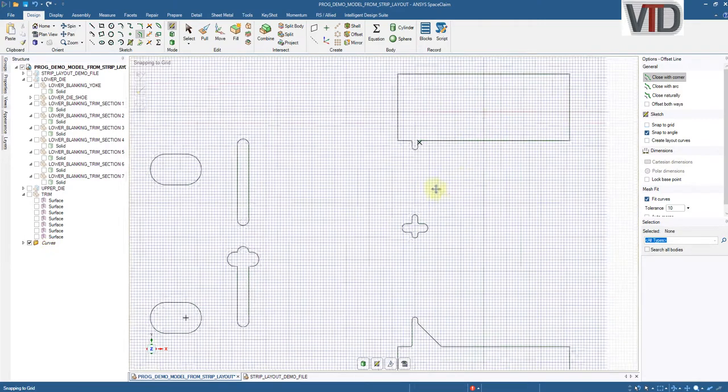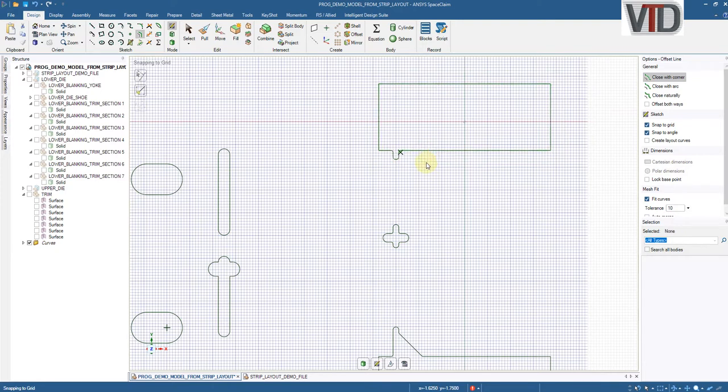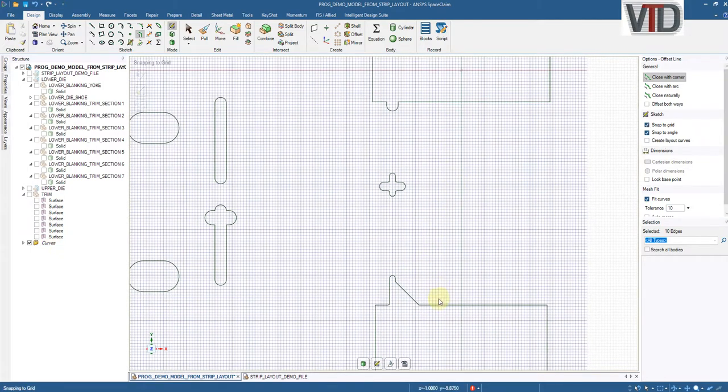Now with this one here, when I double clicked it the first time, it saw that there was basically two viable options here, and it decided to just pick the front face. Now if I hit escape and double click again, it's going to assume that the first double click that I did was not what I wanted. Now it's going to pick the entire chain. So now I can go 0.125. Oops, I accidentally forgot to hit delete. So I'm going to go ahead and double click and delete that.